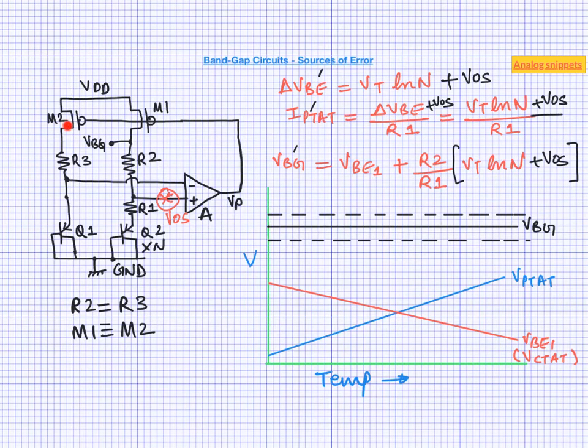And this is because shorting these two nodes makes the current in these two branches very nearly equal even during the startup. And making the current identical makes the startup much more difficult. In some designs during startup these nodes are kept separate, and then once the bandgap has started up these nodes are shorted. On top of these circuit techniques, trimming is frequently used with the bandgap to remove the error associated with the random mismatch and the process variation as well.